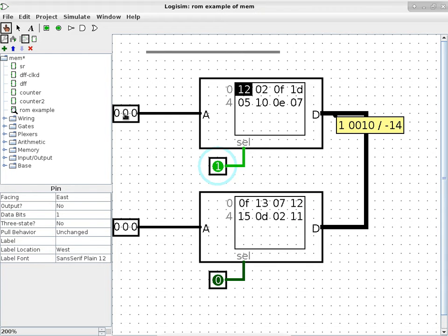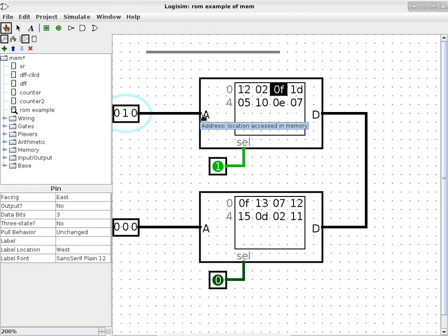We want to make sure that that is the case, so click it, and you can see how this location is now highlighted because it's selected. Because the address bus, remember, is what you put inside the square bracket when we use array indexing as an analogy. And then when we click this wire, we can definitely tell that it's 01111 and the value, and then /15. What is the /15? It's the signed decimal value represented by that bit pattern. But 01111 being 15 is not really surprising, right? Because it is 1 plus 2 plus 4 plus 8, and that turns out to be 15.